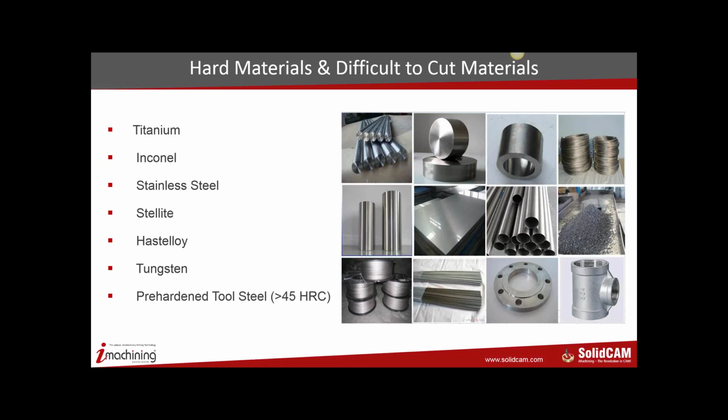The edge of the cutting tool is exposed to a considerable amount of mechanical stress, strain, and heat while machining these alloys. First of all, the main characteristic of these materials is that they have very poor thermal conductivity.